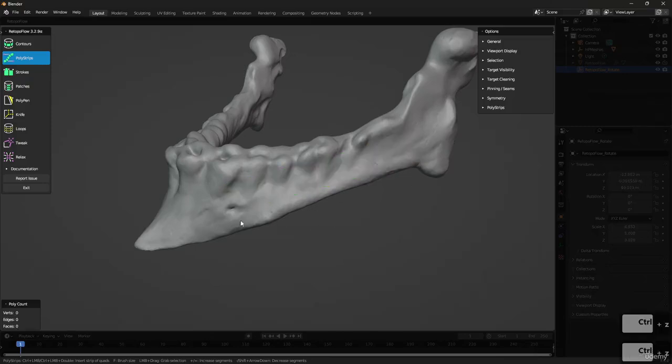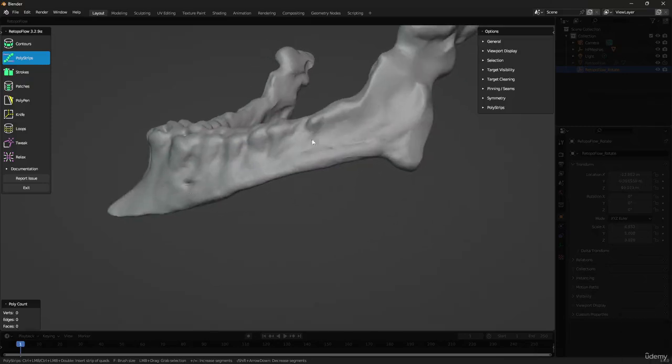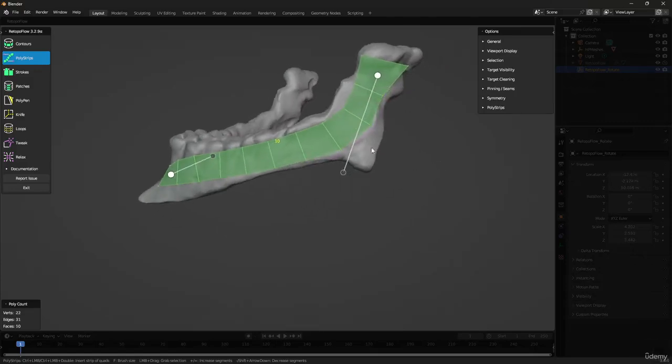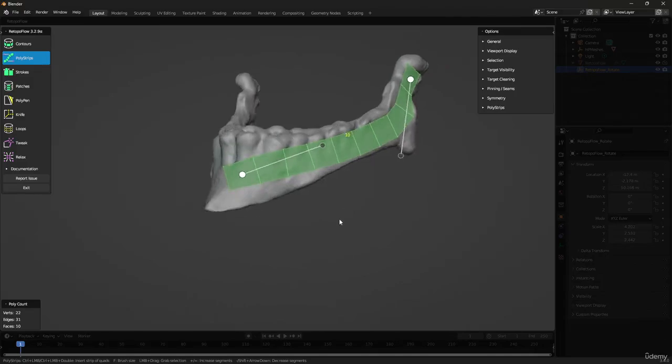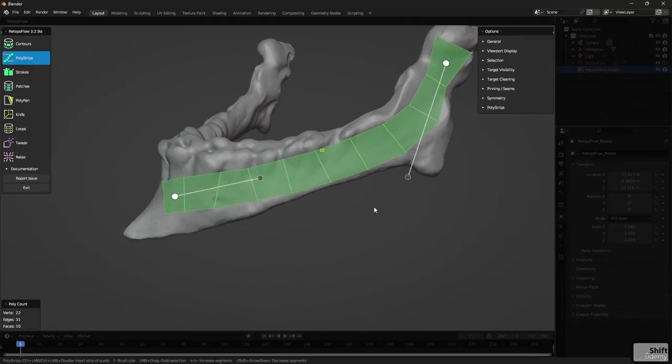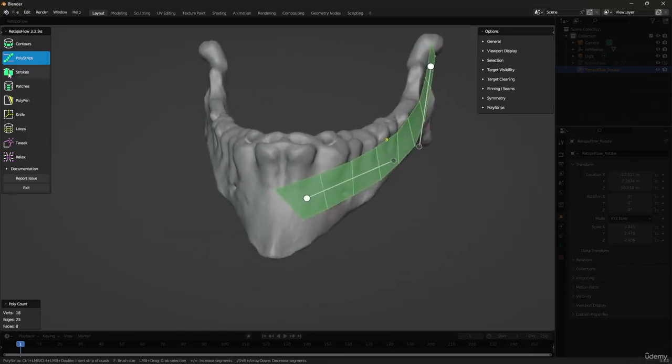This is extremely helpful because imagine inside of Maya having to draw squares all around this place right here. With the polystrips, we can just press Control, draw all the way up here, and there we go. Look at that. We got all of the basic sketching of the elements that we might need. You also get these handles. They work kind of like splines that will allow you to modify these things like what I'm doing right here. And again, if you press Shift and middle mouse scroll, you can add or remove points. For instance, in this case, let's keep it at 8.